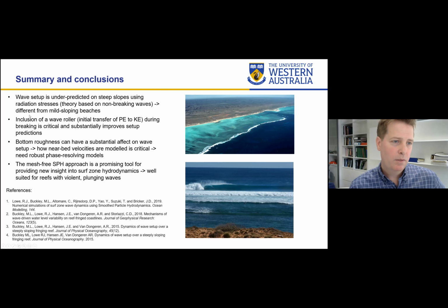The importance of including this wave roller effect, which is really describing how when waves break, the height initially drops, but the energy is not lost. It's going into driving a lot of kinetic energy, a lot of vorticity and so on, and that's delaying the wave forces and pushing those shoreward.